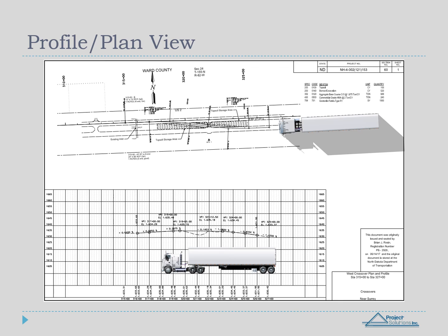Below the Plan View is the Profile View. This is like looking at a truck from the side. This view gives you the contour of the land as it travels across the project. These two views are usually on the same sheet, and in this case, they are on Section 60, Sheet 1.